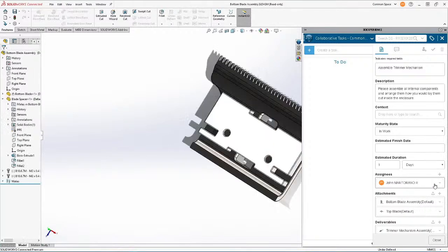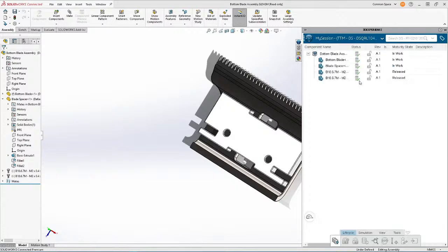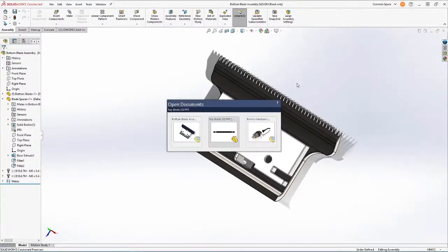And here's the first little pro tip that I'm going to throw in there. When working with multiple SOLIDWORKS files at once, we can use the Control plus the Tab button to switch between open files. And this is similar to using the Alt-Tab shortcut in Windows. Also, as long as I hold the Control key, I can click Tab to change my selection and really just click the one that I want.